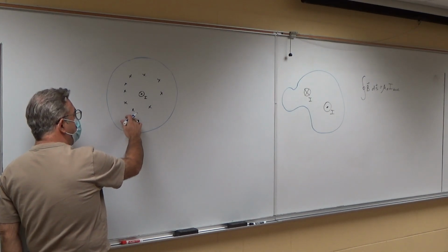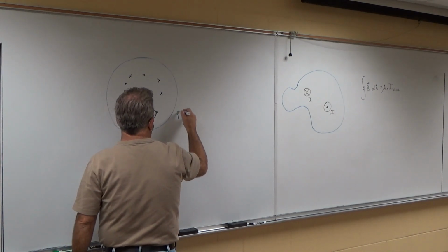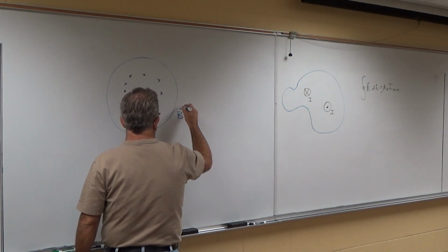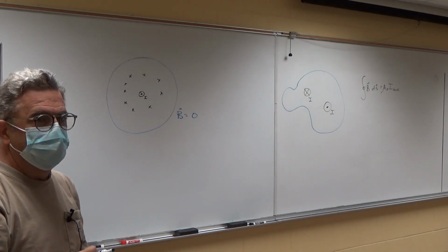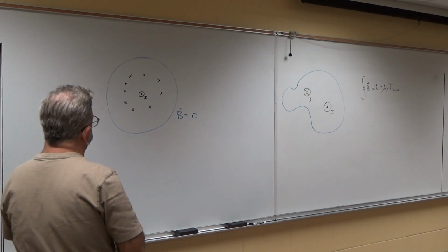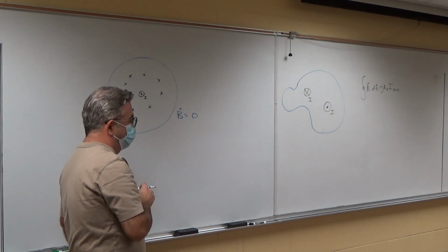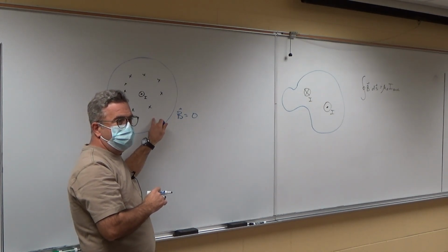But because of symmetry, this being coaxial like this, out here, B is actually equal to 0. That's the beauty of coax. It's quiet. If you have current flowing in it, you don't get an associated magnetic field outside the coaxial cable. You don't get noise.